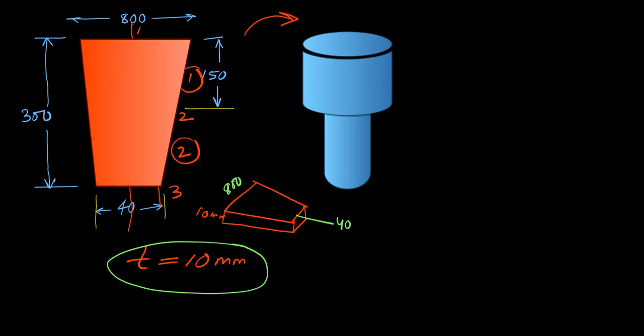We divided this taper section into two elements and three nodes, 1, 2 and 3, where node 2 appears at the middle of this taper bar. Okay, because the total length of the bar is given as 300 and the midpoint is at 150 mm. So that will be the midpoint having node 2, and these sections are converted into a finite element model like a stepped bar. Okay, so all dimensions are in millimeter, remember.